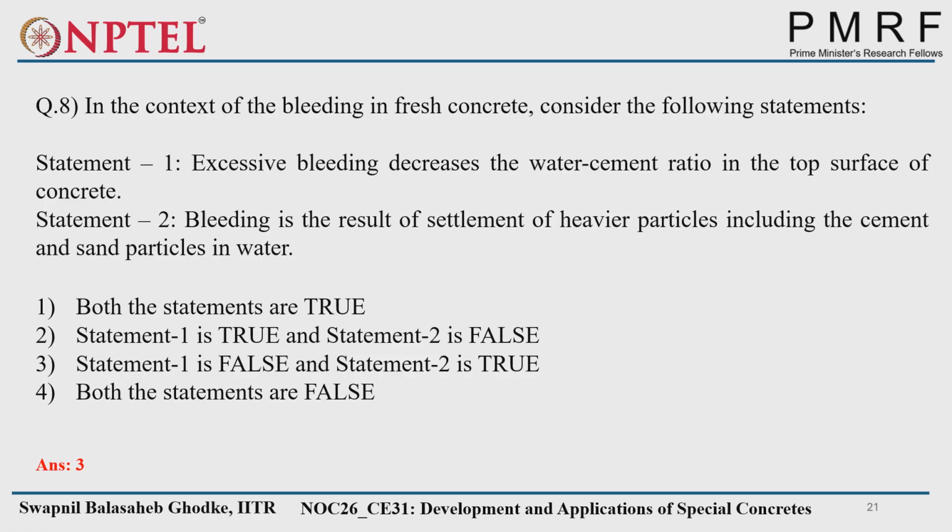That being compensated is very difficult, but curing is the most acceptable way. With proper curing, you are providing external water for the hydration. It will not depend on the pores of the concrete. It will not penetrate, but some amount of strength will be lost in that way, like through the bleeding also, because more hydration will not happen. Maybe that unhydrated cement will act as a filler only.